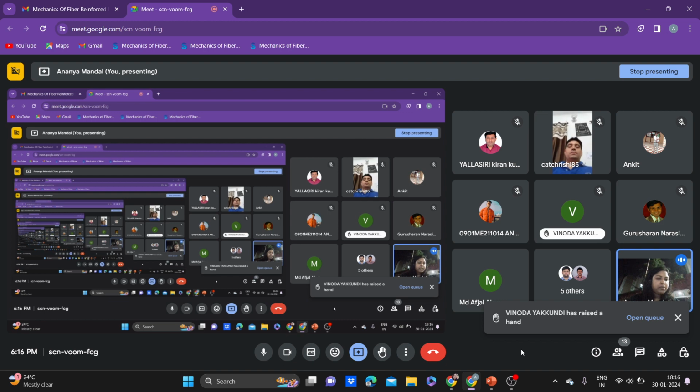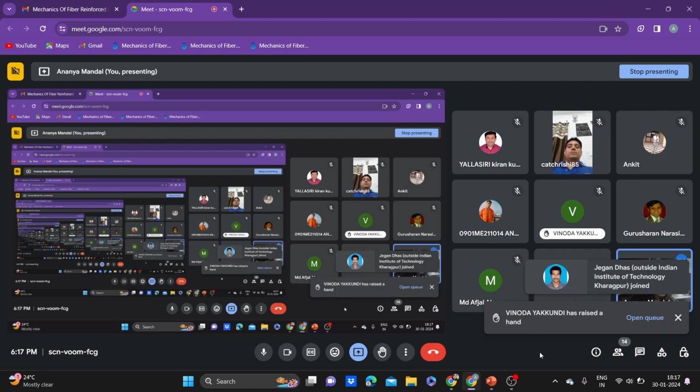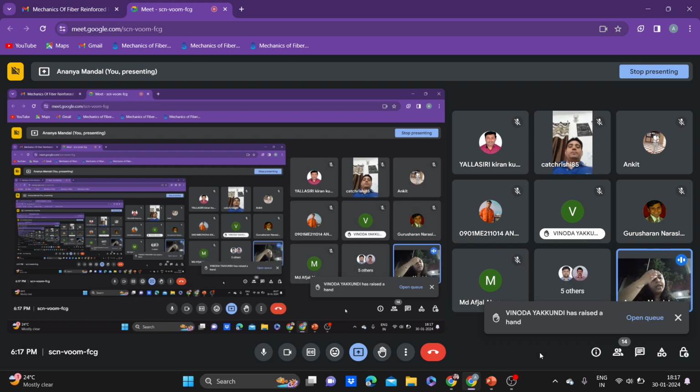There are some exceptions, as this composite definition came very early. Now there are new things happening, like in the course, Sir also talked about nano composites. They have nanoparticles and all. So if you see through the size, then obviously the size is smaller than micro, so you can say that. But the earlier definition and the proper definition of composite is that we can differentiate all the components through our naked eyes, and it is macroscopic.